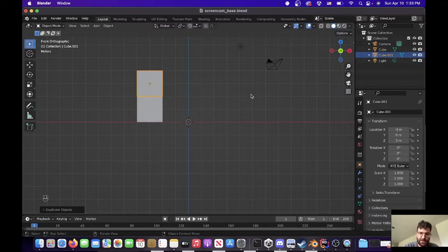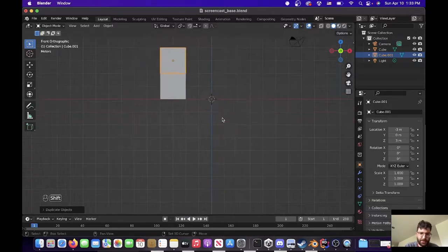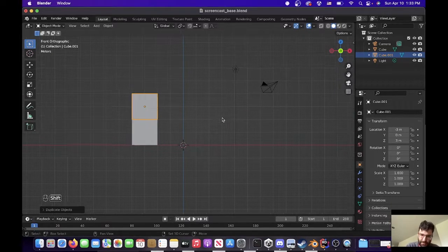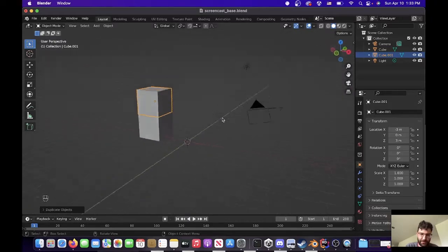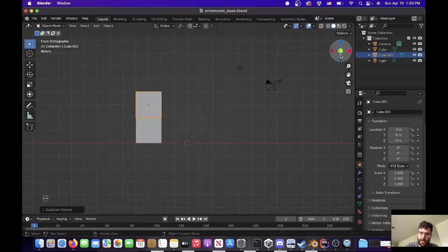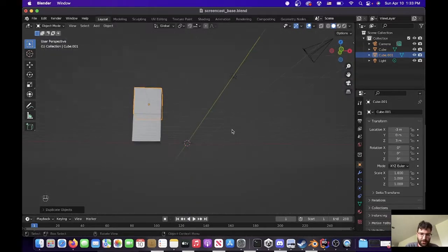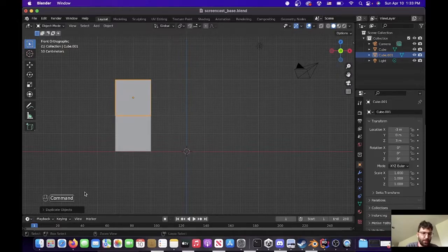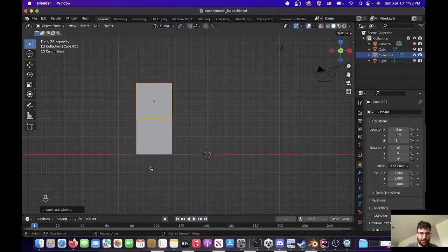I haven't done this in a minute, so I don't remember. There we go. If you hold Shift and use your mouse pad, you can pan. If you don't hold Shift, you're gonna orbit. And there's one other thing. How do you zoom? Hold Command and you can zoom. If you look in the lower left, I've got my keystrokes visualizing so that you can hopefully follow along.